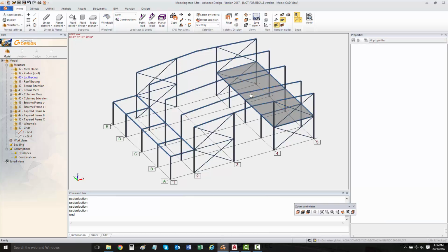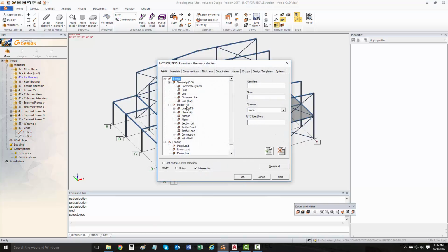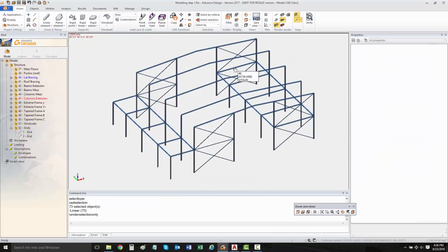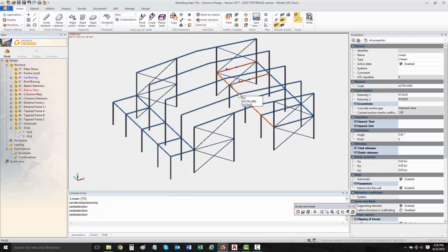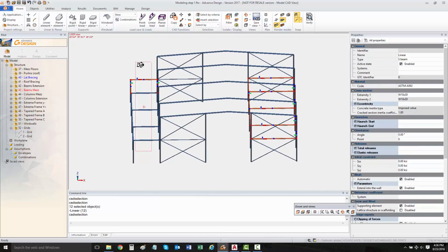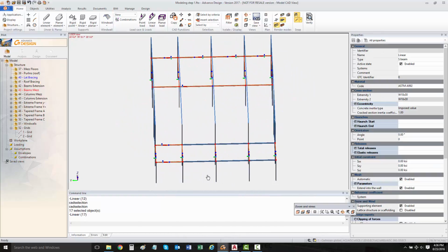What I did is I modeled beforehand, and so what I could also do is limit by selecting. I could remove anything that's a planar element here to be able to select our beams a bit more efficiently, so that we don't have those other elements hiding behind. I have filter functionalities and sort functionalities here. I'm going to just turn it around so that I could select all these in one shot instead of having to select them all individually.